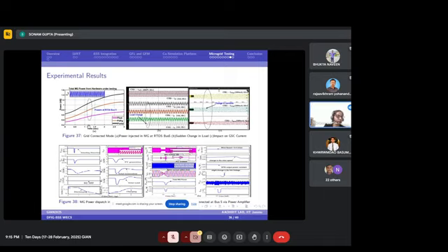So this is the RTDS. These are the RTDS signals, which are the power outcomes from the hardware that are sent back to the RTDS. And we have tested it for a sudden change in the load, and we have seen the impact on the grid side converter currents and the impact on the network as well. Whatever simulation results we have seen for the simulation network will be validated in the hardware testing as well.